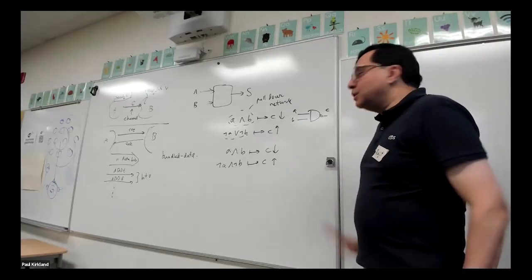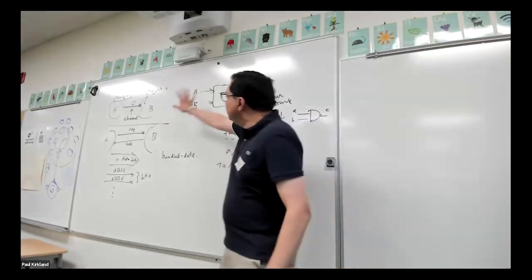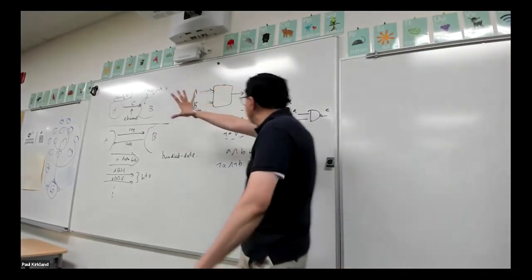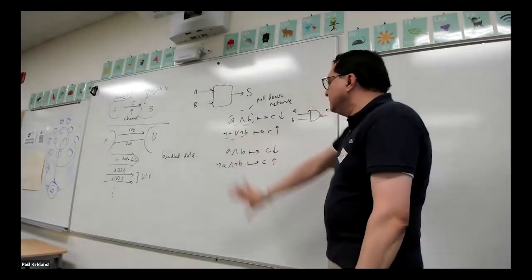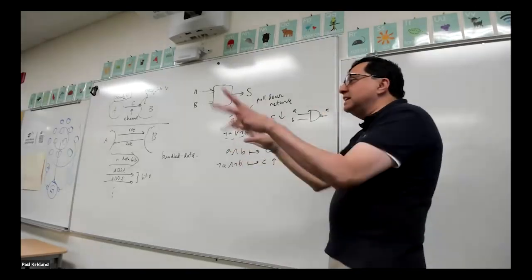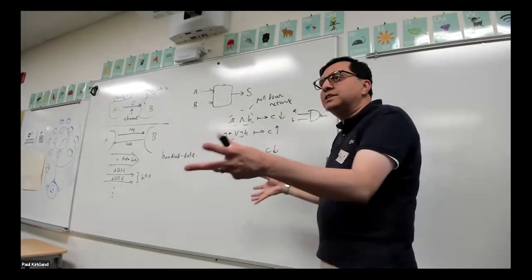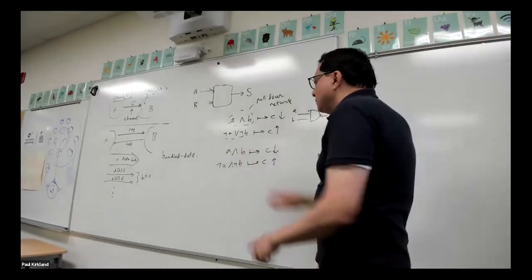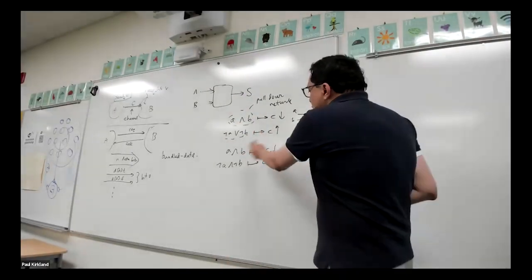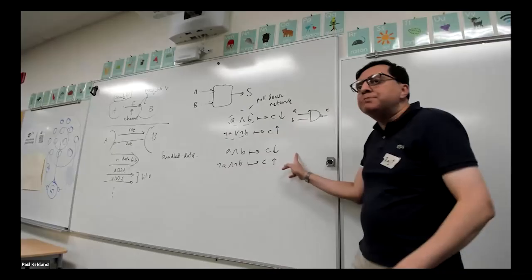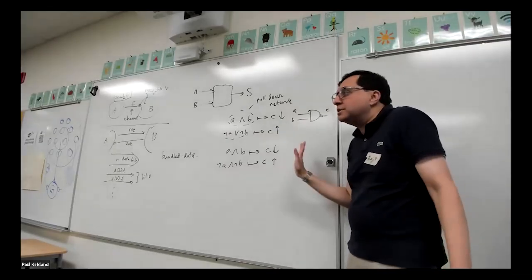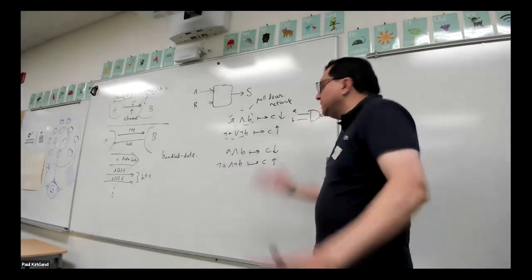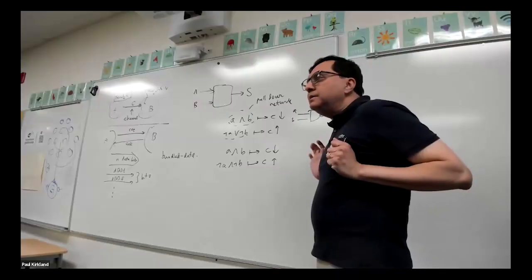Okay. So the question is, we go all the way from the behavioral description to a whole bunch of things like this. Each of these gets turned into basically a cell, right? You find all the unique versions of this. This is where you do sizing, all your circuit level optimizations, fold things. Normally, whenever you have a state holding gate, we put a keeper or a staticizer circuit on it to make sure you don't have to worry. And that's it. That's how we build a chip, right?